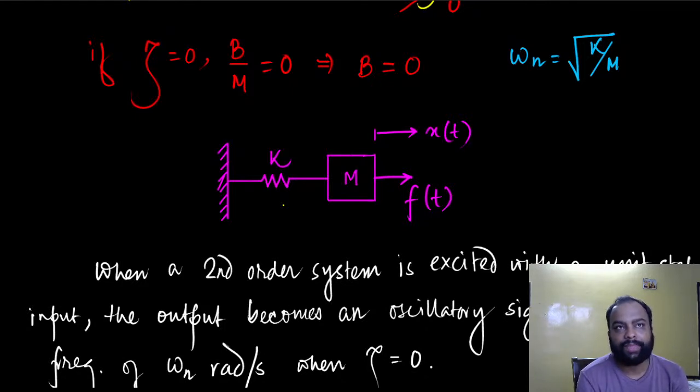Of course, you already know that an ideal capacitor can never spend energy. If you apply a sinusoid to a pure capacitor or a pure inductor, then in one cycle of the sinusoid, the capacitor or the inductor will store energy, and in the next cycle, it will release that energy back to the source. Then again, in the next cycle, it stores energy and releases it back to the source, and that keeps on happening. So capacitors and inductors cannot spend energy. They can only take energy in one cycle and release it back to the source in another.